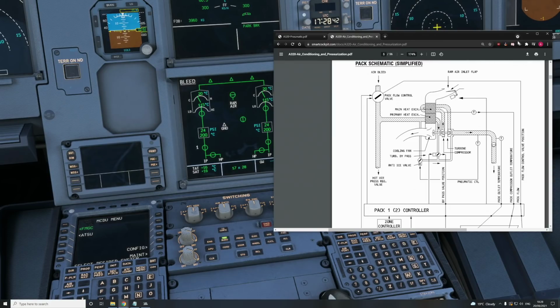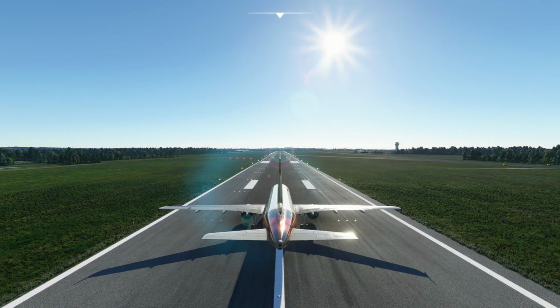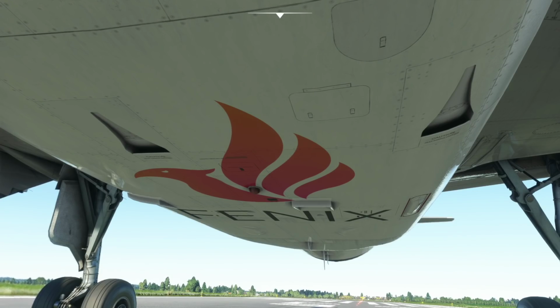The interesting development anecdote I wanted to share with you was about these ram air inlets. When we first designed this, like I mentioned, it's a physically modeled system. So when we started closing off this ram air inlet, and when the airplane was sitting on the ground for a while, something was missing. We were wondering why we were constantly getting overheats.